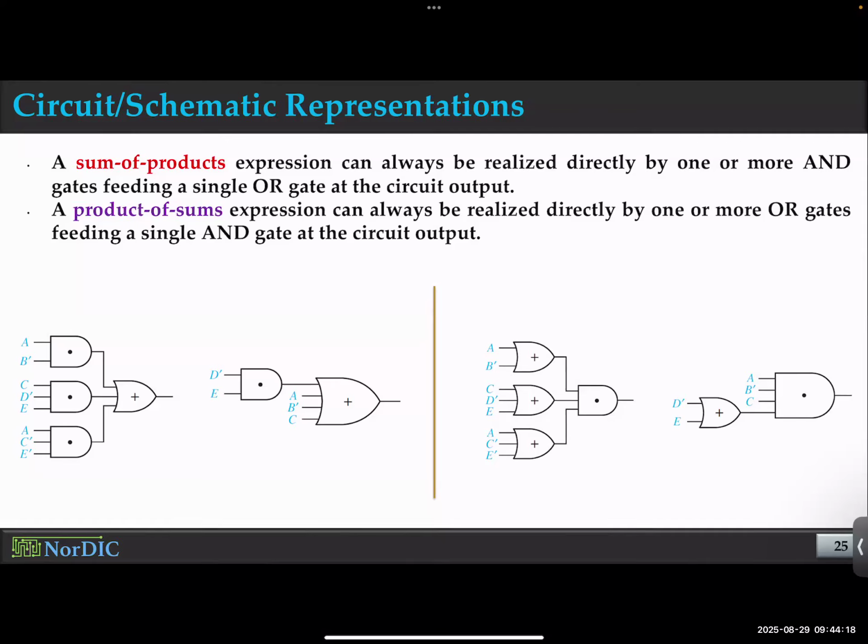So if I am reverse engineering, what I'm going to do, I'm going to look for the last OR gate and see what it is adding. So these are definitely going to feed into all these other gates. And then I'm going to look for all the ANDs. So basically, I can spell out the function quite easily. So that's the challenge, because it is so uniform, anybody could reverse engineer. But also, it is so uniform, it is easy to mass produce.